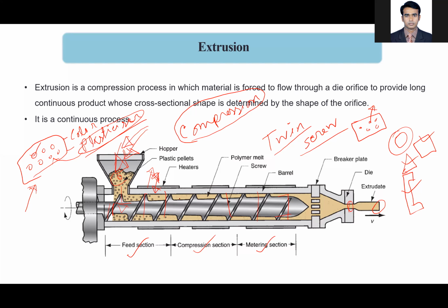Compression is required. And the second one is to increase the pressure or compression. If we do not increase the compression pressure, then the problem is the extrusion speed will be very low, and there will be a lot of other defects. When I go to the defects, I'll show you what happens for low speed or low pressure set here.